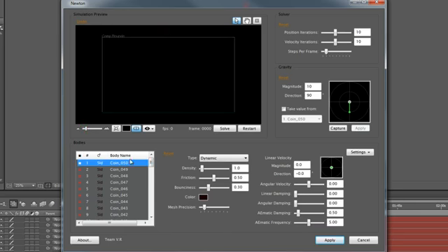Once we pick up an element or a body or multiple bodies, we can adjust their characters, such as what type they are, their density, their friction, their bounciness. Color only refers to their appearance in the simulation preview, and their mesh precision. Over here we have the solver, the gravity, which controls which way and how much the gravity would influence the bodies, and the velocity and damping in this section.